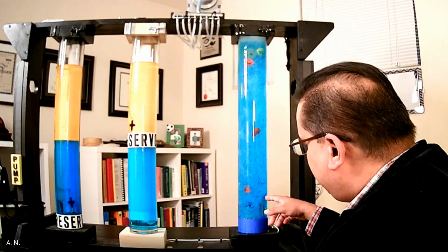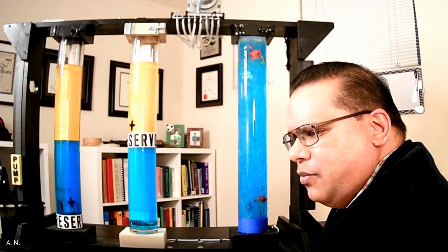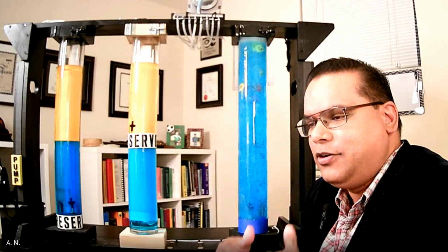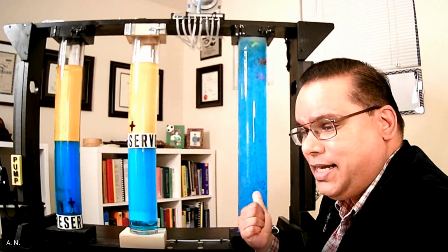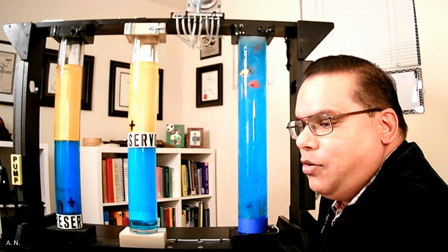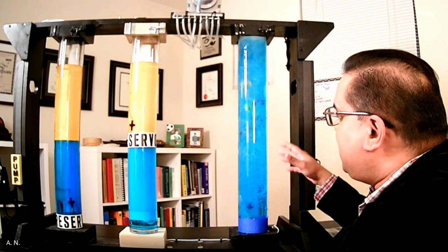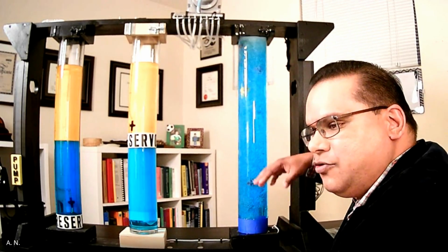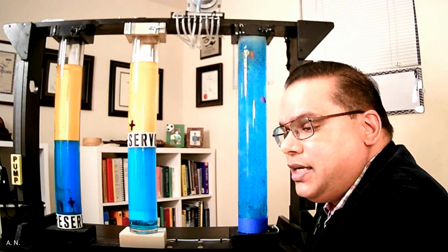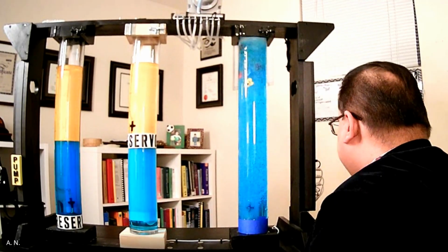So now we see some behaviors here of these fishes going all the way down to the pump, right? So that's counterintuitive, isn't it? Unless you had a good understanding of gaseous liquid columns, which is the recycling nature, right? And again, this is a tiny gas rate compared to the gas rate that you have in your wells. This is just an off the shelf gas pump, right? So the point is here, you're going to have all of this structure, all of these recirculations going on inside of your systems, and you can design the systems to take advantage of those flow reversals, right? Those multiphase flow reversals. All right.